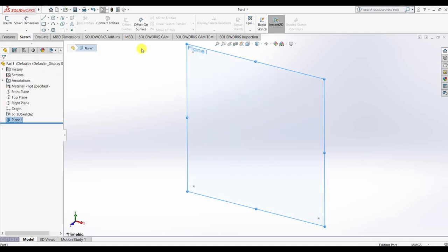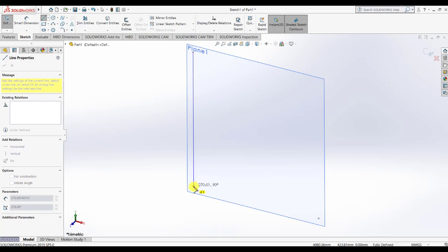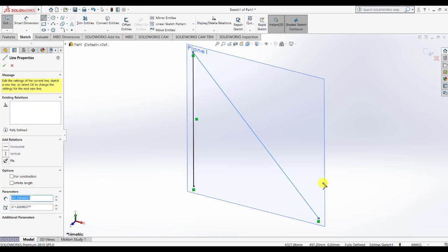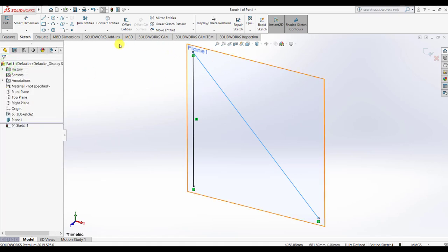Again, what I want to say with this is, since I simply joined the points with straight lines, you can give it a different shape as well. The only thing you have to take care of is that the points are not moved from their locations. I can give different shapes to my wishbone, whatever I want, but I don't want to move the points from their state, because this follows the geometry. I can give any shape I want, but the geometry should not be changed.